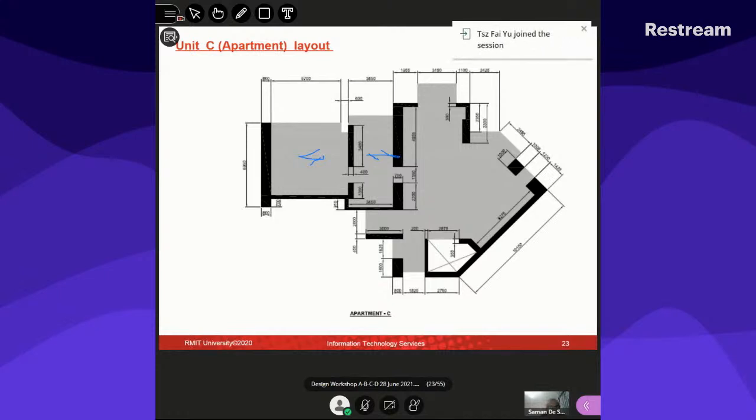I would suggest that in this case, you have a couple of options available to you. One thing is getting a little bit of an edge beam to support this very small cantilever. I suspect if you look at the plan properly, there will be a possibility that there's some member.